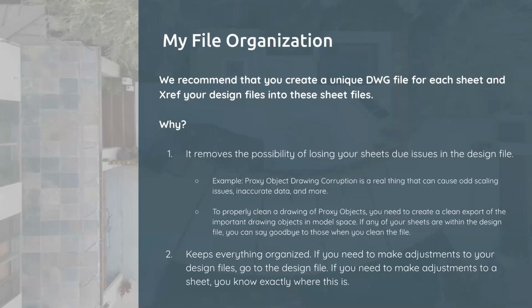And the biggest reason is number one here, and that's it removes the possibility of losing your sheets due to issues in the design file. And probably the biggest example of that is that proxy object drawing corruption is a real thing and can cause devastating effects to your drawing files.